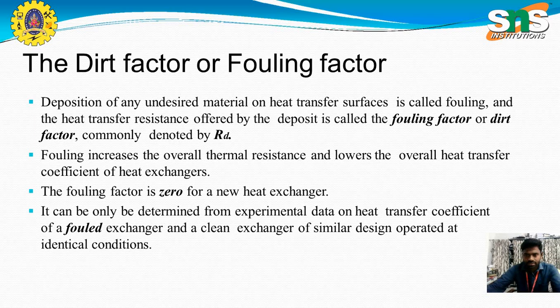These factors directly affect the heat exchanger efficiency. So if you want to get proper or higher efficiency of heat transfer, you have to remove all those depositions on the surface. For the heat transfer rate, the surface area plays a major role in attaining the maximum heat transfer efficiency.